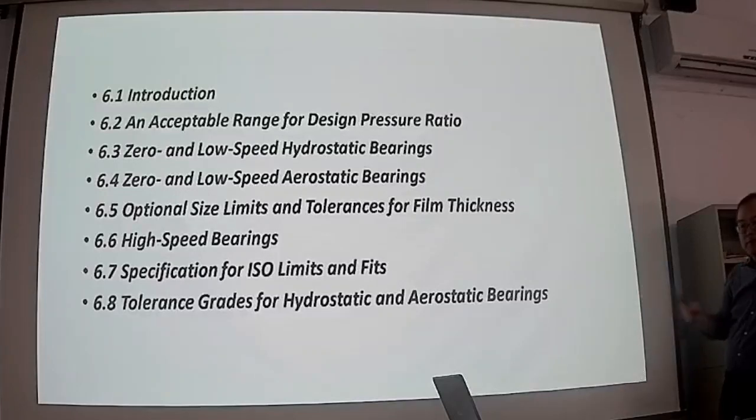Overall, for your manufacturing of the hydrostatic bearing or aerostatic bearing, you need to carefully select the manufacturer or manufacturing factory because the dimensional tolerance is very tight. So you should pick the manufacturing factory which has very good quality control for their product. Otherwise, you will have a problem for your hydrostatic bearing.